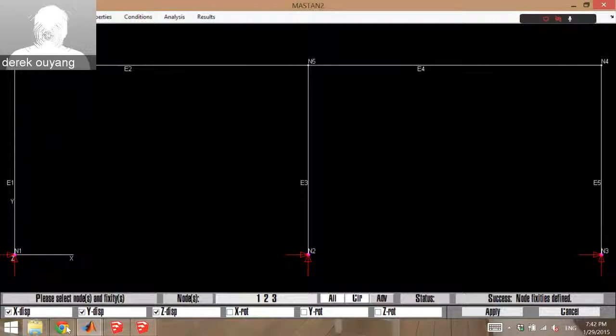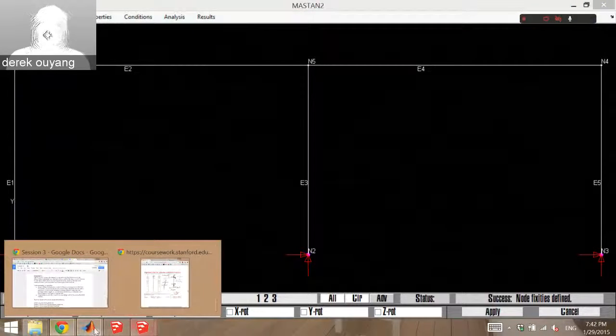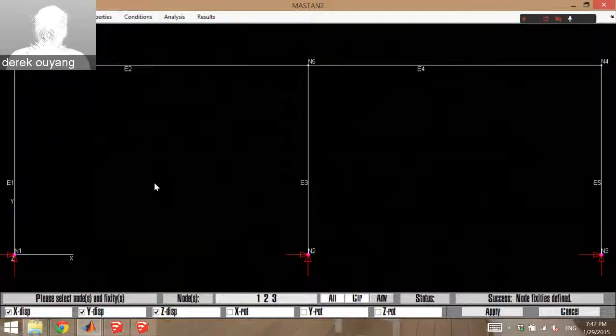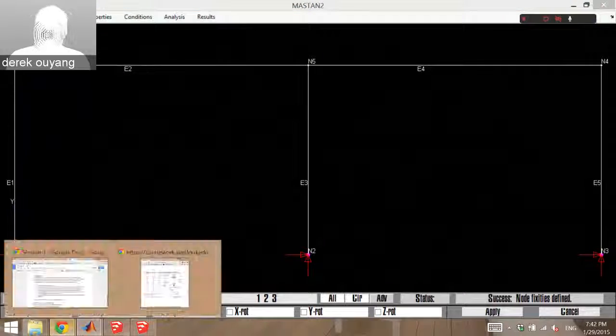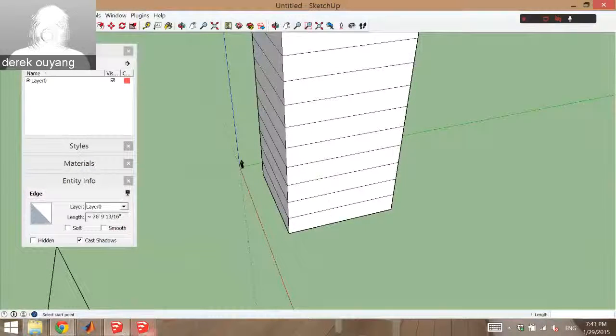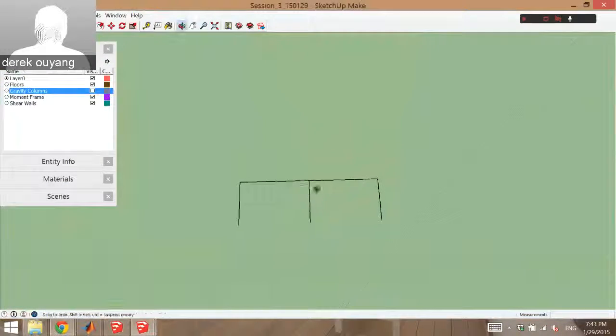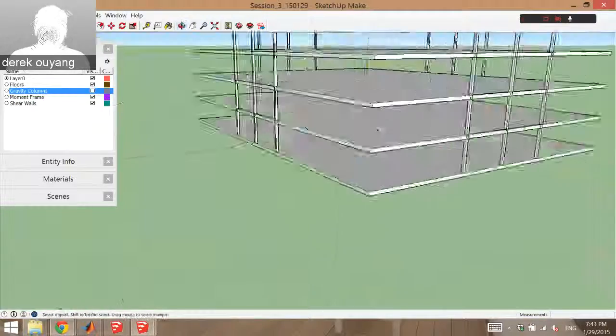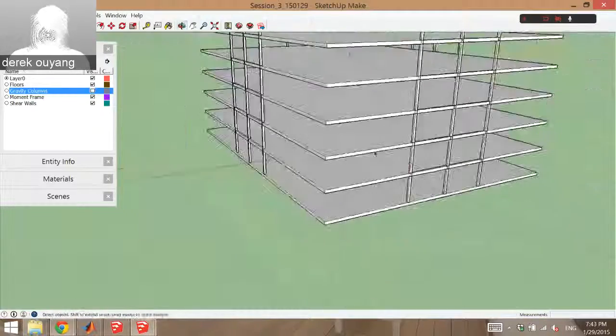So let's assume that the way the building is designed, all the wind loads on a given wall will get into the floor system through the load path. Since this is the bottom floor of the building, and let's say the wind load, I think I had it as 35 psf.